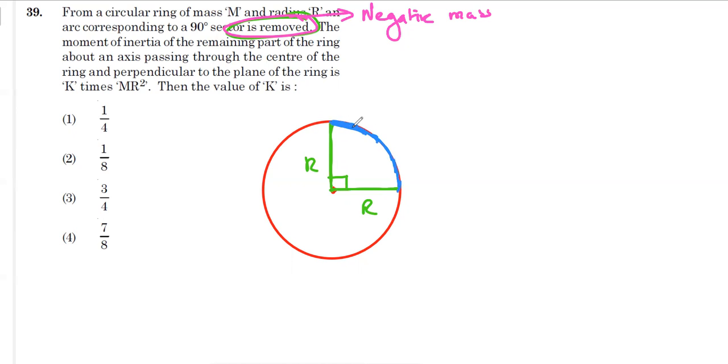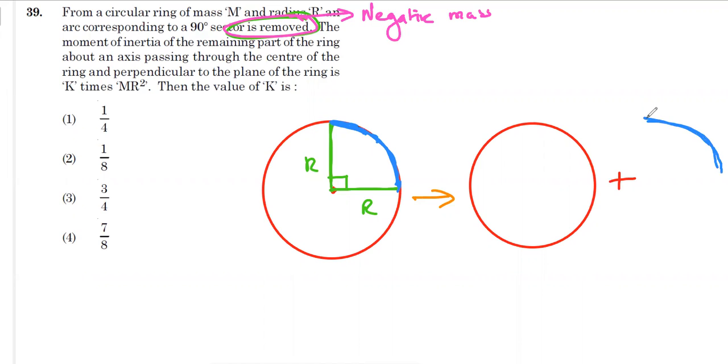Okay, அப்ப என்ன மிச்சம் இருக்கு அப்படின்னு பாத்தீங்கன்னா, ரிமைனிங் portion இது மட்டும் தான். இதுக்கு என்ன moment of inertia கேக்குறாங்க. Remember எப்பவுமே removed நாம என்ன பண்ணுவோம், we'll consider it as நெகட்டிவ் மாஸ். அப்ப என்ன பண்ணலாம், இதை வந்து நான் 2 போர்ஷனா மாத்தலாம். So I say that I have 1 full ring. Okay, as usual எனக்கு அந்த ஒரு full ring இருக்கு. அதோட நான் என்ன assume பண்ணிப்பேன் அப்படின்னா, I have plus this portion of this, 1/4 of the ring is present. இது ரெண்டுத்தையும் add பண்ணுவேன். But I say this mass is negative mass.